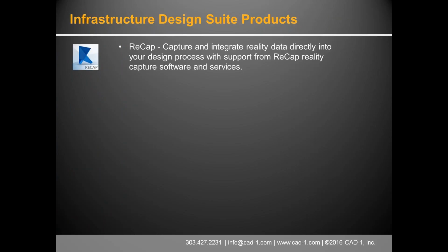Yeah, so Recap actually has 2 different pieces to it. It has just the point cloud aspect, so it can take multiple point clouds and register them together, and you can process massive amounts of point cloud data within Recap. So if you ever have to get scanning done, you can do that. What we did with our building is we used Recap Photo, and that allowed us to, as Lawrence said, take a drone and fly it around our building and take pictures of the building. And then Recap actually created the point cloud for us from the imagery.